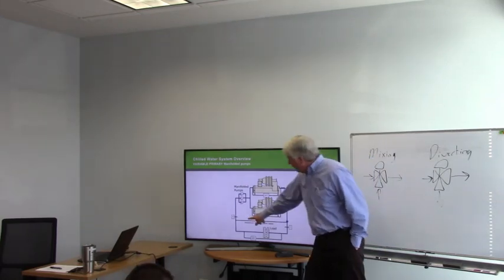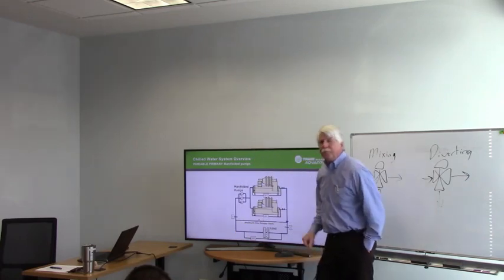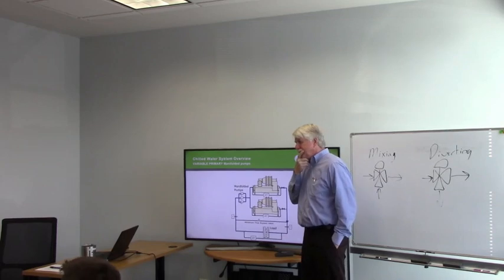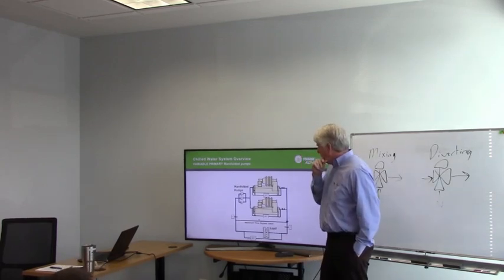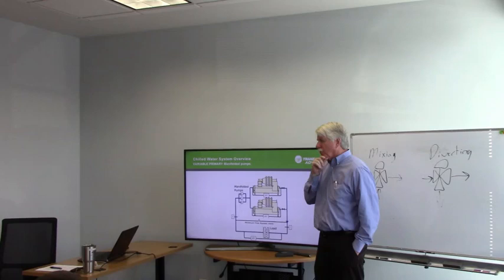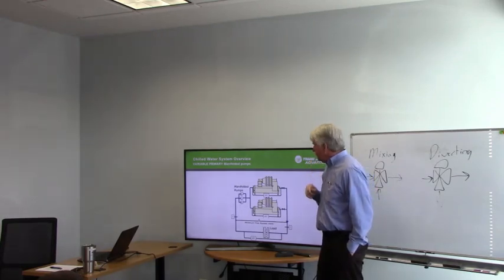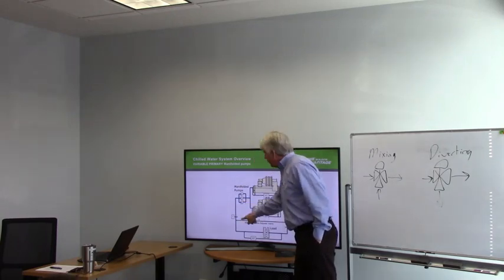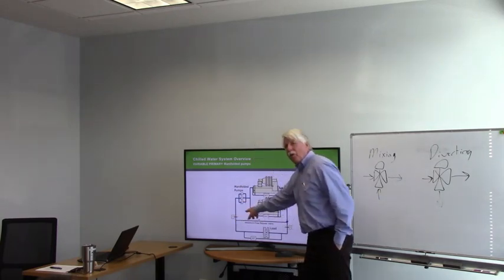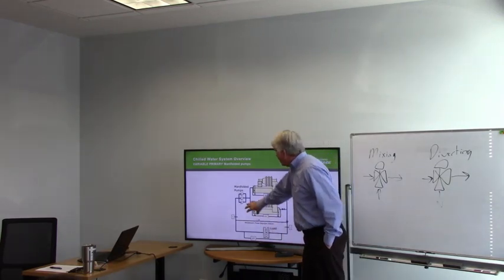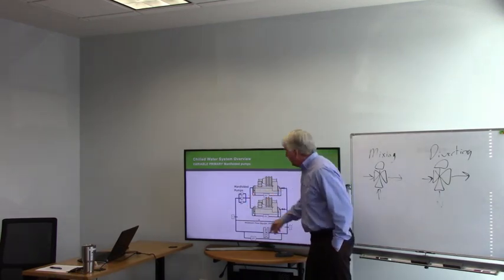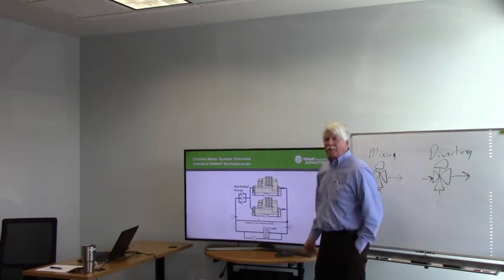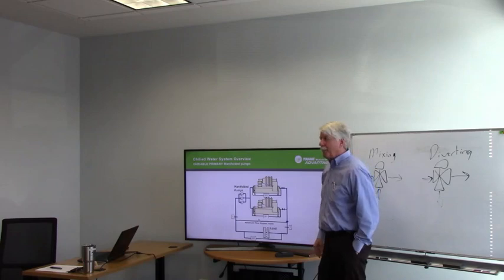What happens if I put the return temperature over here? It's not going to be a true return temperature sensor. Why not? Because it's before the bypass. So what's going to happen when that bypass is open? When the bypass is open and the water's going through here, this temperature is going to be colder, which really tells me there's less load on this plant. If I put it here, it's going to be significantly warmer, and that's going to tell the plant I have a big load on me.